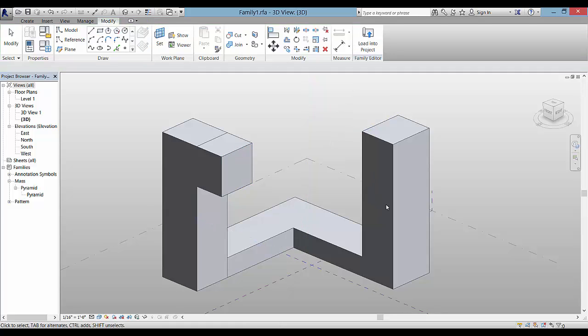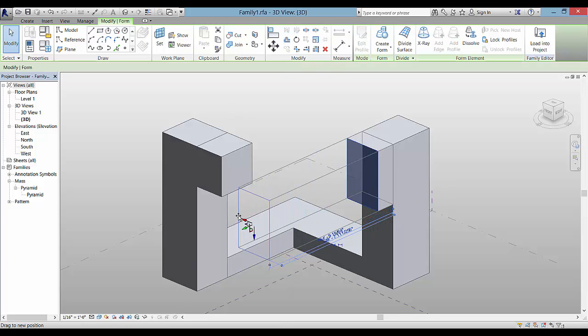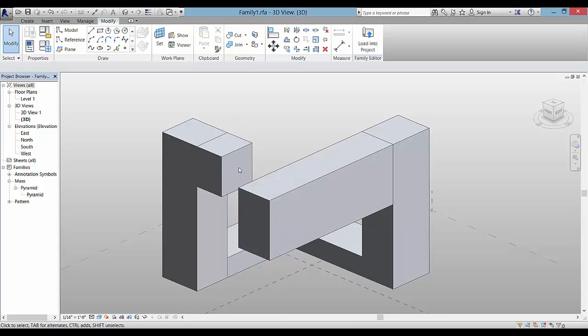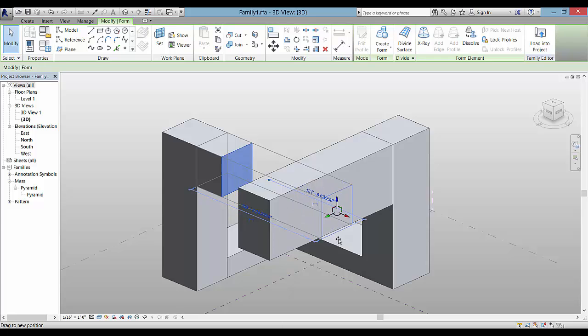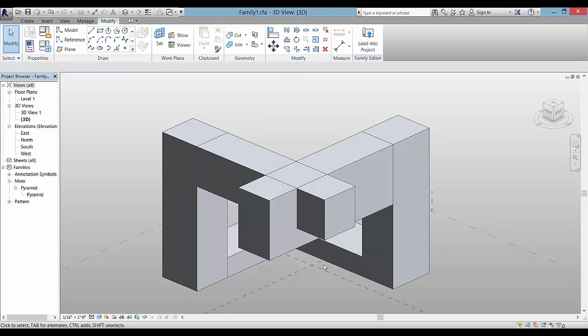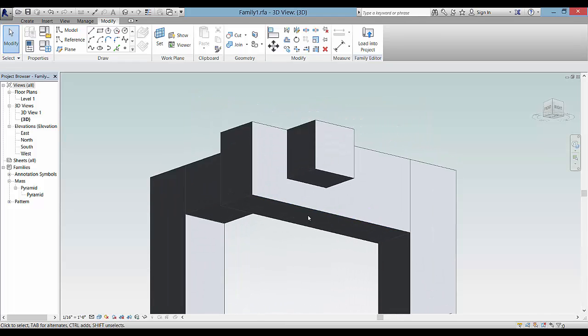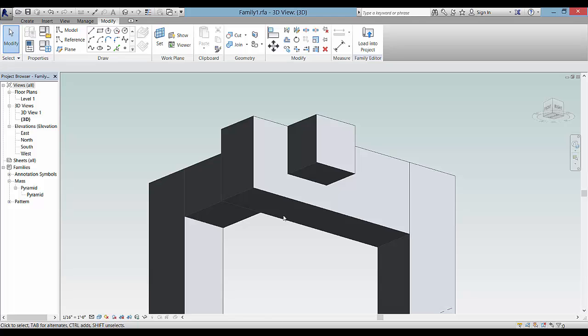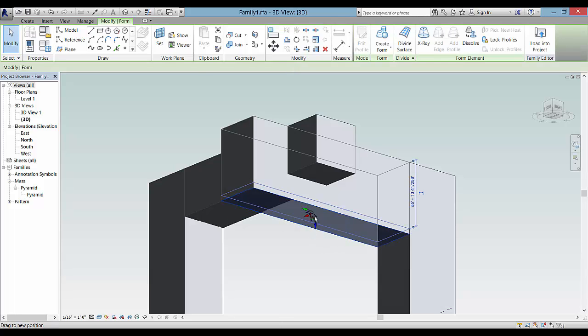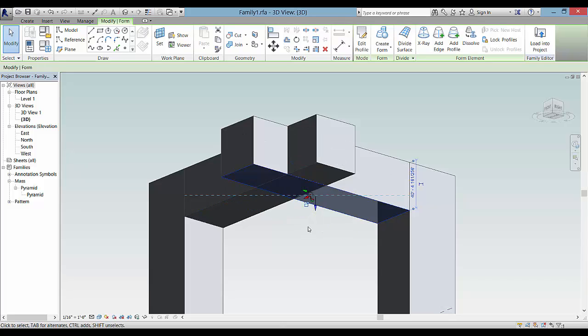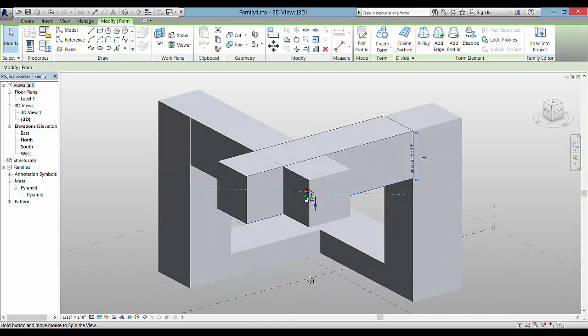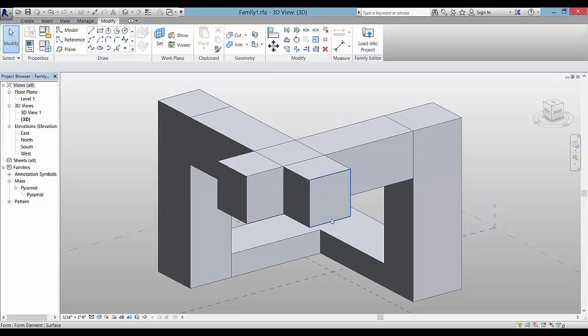And here, if you have in AutoCAD your allow and disallow UCS on in the status bar, you can draw right on the face. Here in Revit, we are automatically able to draw right on the face of the solid. And so in this example, I'm showing you that when you extrude the face, it will automatically read the geometry of the existing planes. And so in this case, I'm able to take these faces back until they line up and they kind of snap into place to clean up this corner.